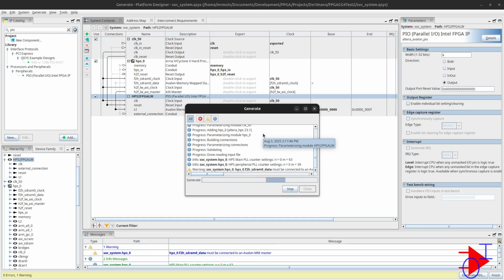This is the key point of this project component: you generate the HDL, and this compiles a series of other files. We will not include all the files, we will just include one file, but that one file will allow all the other components of this project to be included in our main project, our VHDL project.